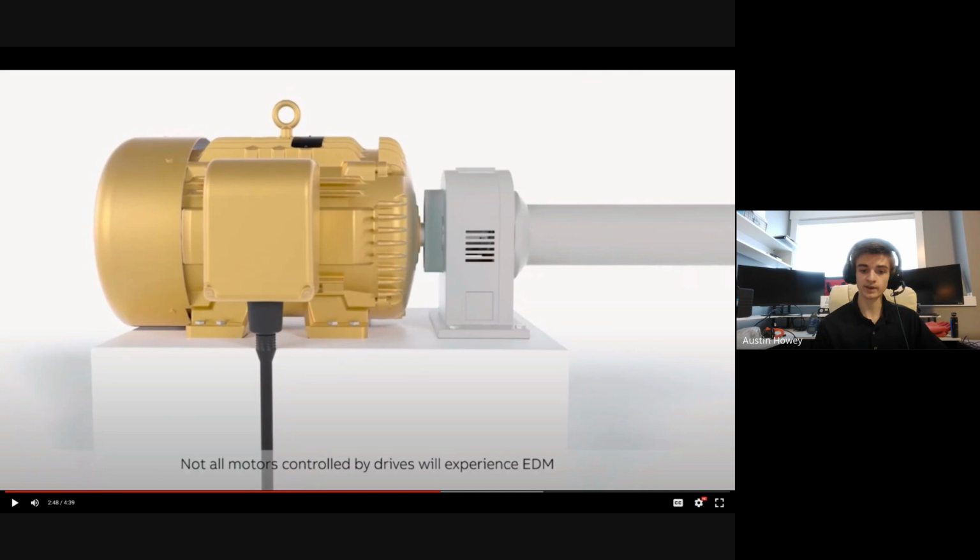And I see a lot of fan companies go extremely cheap on bearings, and I don't know why they do that, because bearings are not that expensive. I mean, we're talking about $300-$500 for premium bearings compared to $100 for non-premium bearings. So you might pay 2x on that, but you're going to get 10x life on it. So be very careful on the internal components too.